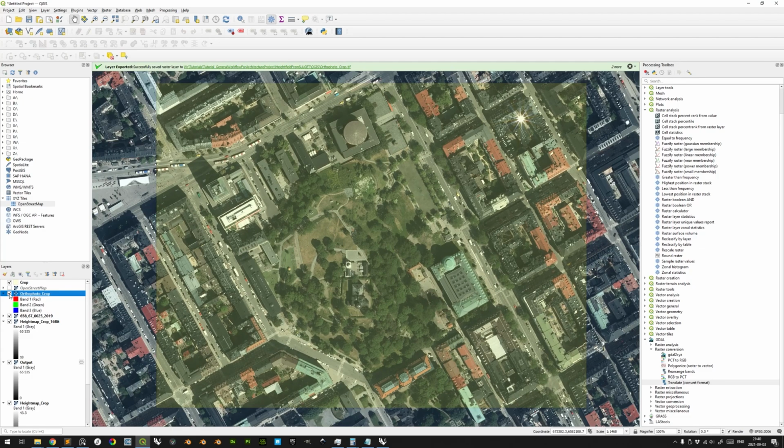And you see here that there is a slight difference between the 2 projected images, and that is because the one that we exported now had its extents at integer meters, while its actual resolution was 0.16 meters per pixel, which means that there can be a misalignment of such a proportional pixel. All right, this has already been exported, so just navigate to it.